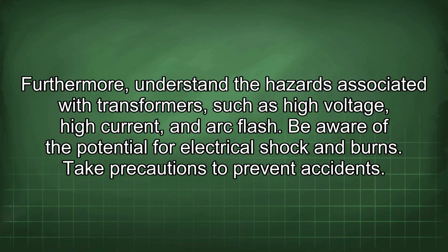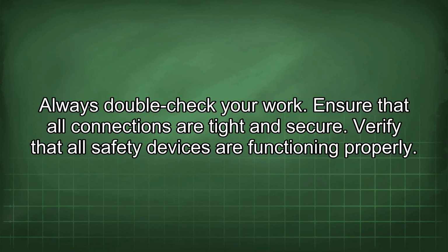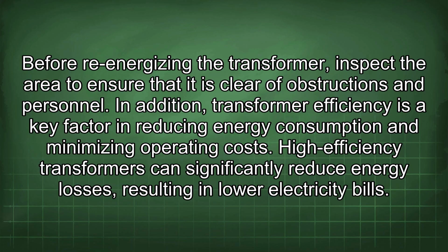Furthermore, understand the hazards associated with transformers such as high voltage, high current, and arc flash. Be aware of the potential for electrical shock and burns. Take precautions to prevent accidents. Always double-check your work. Ensure that all connections are tight and secure. Verify that all safety devices are functioning properly. Before re-energizing the transformer, inspect the area to ensure that it is clear of obstructions and personnel.